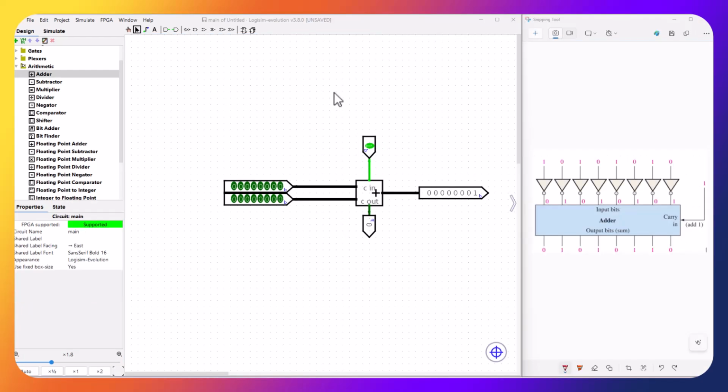Okay, so now we know how the adder works. It takes two inputs, you can see them here, and it gives me the addition or the sum of both. And if there is a carry, it will take that. This is called the carry in. You can see C in, and if the operation leads to a carry out, then this one will be indicated. But we are not concerned by the carry out when we try to implement Figure 2-3.